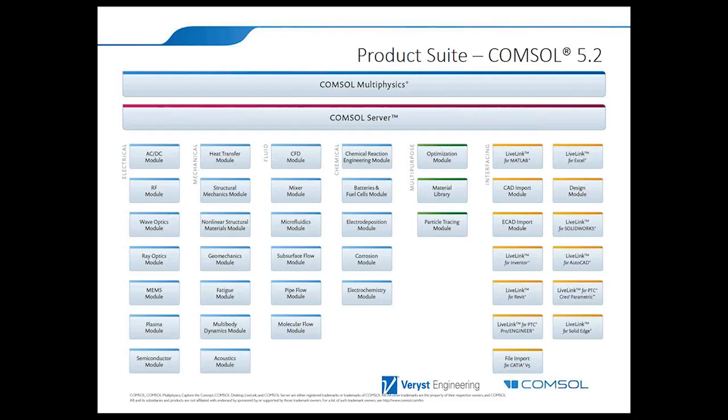All right, thank you, Nagi. So for another very common question we had today, how do you determine the thermal and electric impedance between electrode and tissue? That depends on the materials, the contact pressures, and the roughness. So we typically estimate upper and lower bounds of these values based on the problem. And like I mentioned for the previous question, we can sometimes just test these bounds, see if they make a difference. And if they don't, it's good. If they do, then we've got to do custom experiments to obtain these values, and or maybe calibrate to existing bench data and so on.